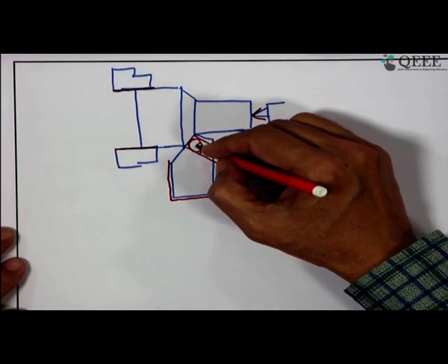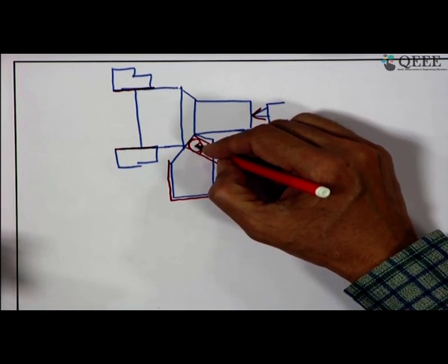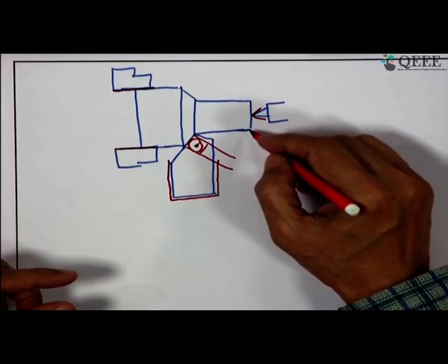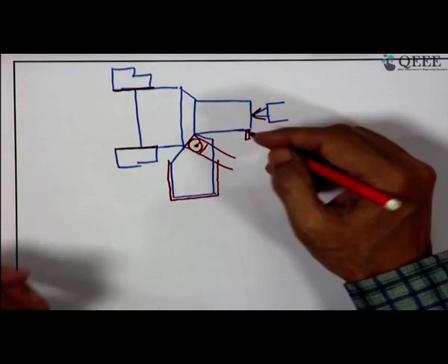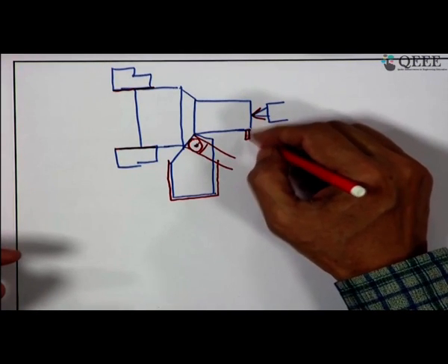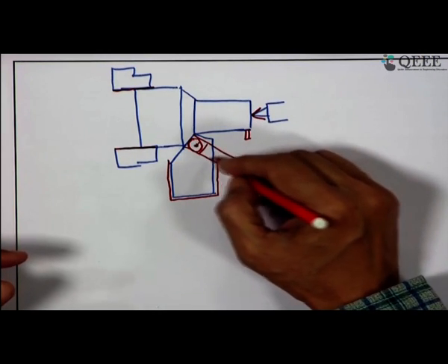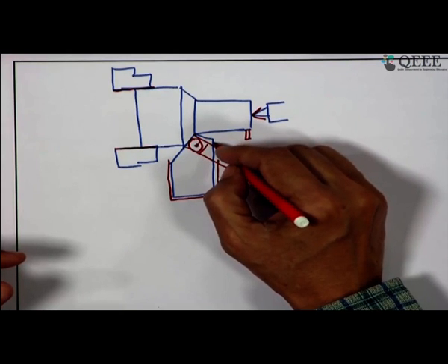So, this becomes your generator of thermo EMF, it acts like a cell. So, you have a cold end, cold junction. Here you can have one carbon brush or copper roller which will roll over it, and from the tool side, this is the chip, you take one tapping point.